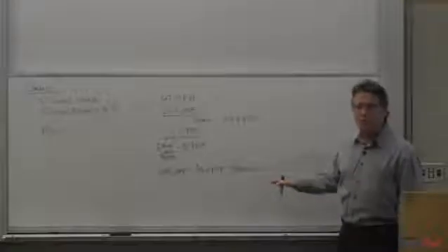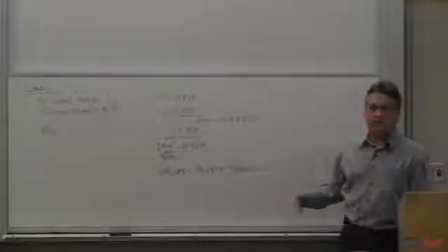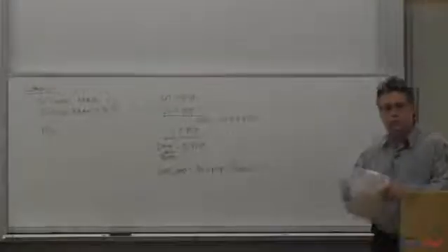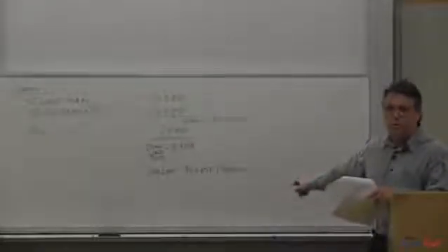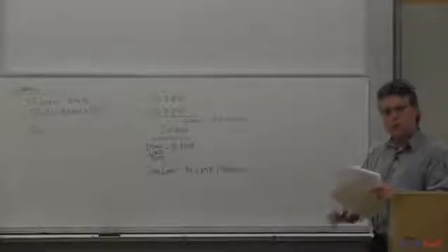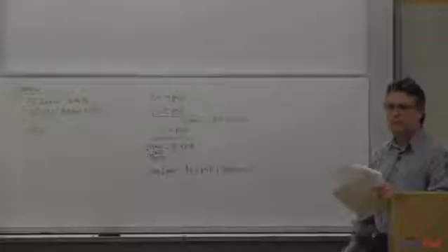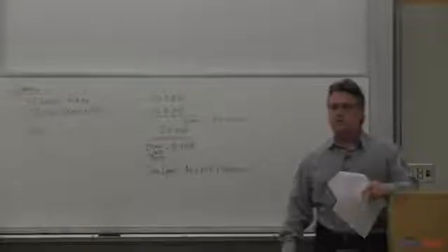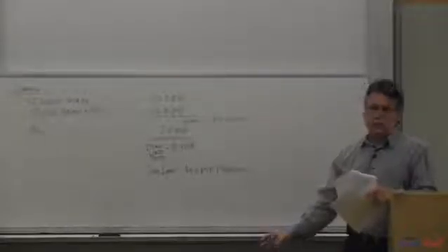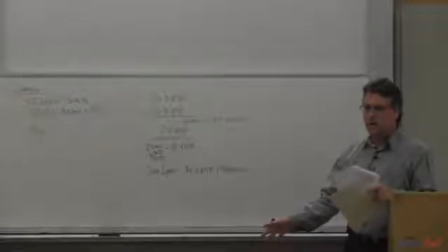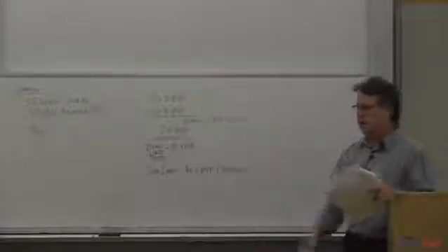Live load comes out of the code itself. The code will just tell you what the design live load is. It depends on the occupancy. If it's a hotel or an apartment, it's going to be 40 pounds a square foot. Parking is also 40 pounds a square foot. Retail stores are 100 pounds a square foot. Balconies are 60. You'll end up memorizing these. There's not that many. Light storage is 125. Heavy storage, 250. But there's a live load table, and whatever the occupancy is that you're designing, you look that up, and it comes out of the code.